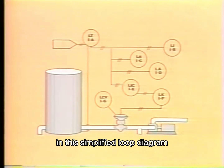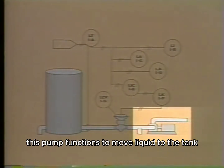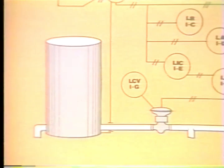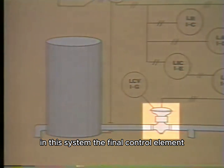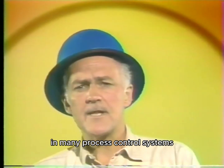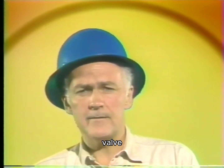In this simplified loop diagram of a level control system, this pump functions to move liquid to the tank and other parts of the system. Even though there are many different types of pumps, this symbol can be used to represent the pump in this system. To maintain the level in the tank, the amount of liquid flowing through the system must be controlled. In this system, the final control element, which is a level control valve, functions to regulate the flow. In many process control systems, the final control element is usually a type of control valve.